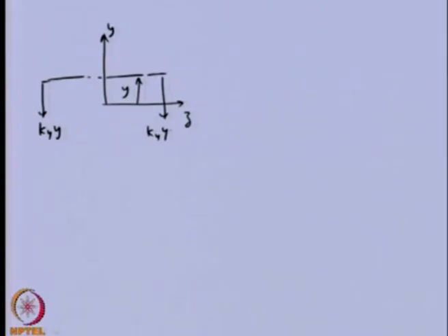And apart from this, this is the center of gravity position. So, we will have a force in the x direction as centrifugal force, this one. This force we can see separately, how this unbalanced force is coming. So, let us see the rotor in the xy plane.